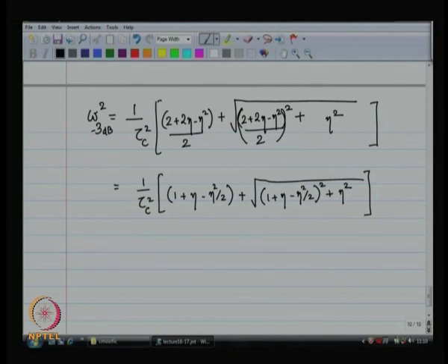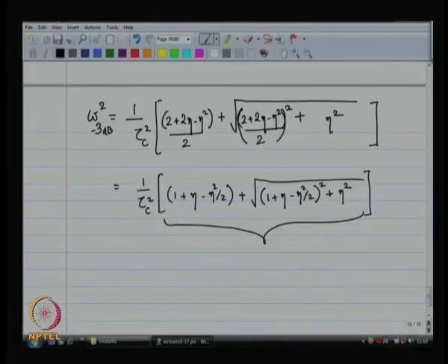So, first of all, when is the bandwidth going to be more than the original? Whenever this factor is more than 1, I am going to get it to be more than the original. And when is it going to be greater than 1? At what eta is this equal to 1? We can solve for that eta. Okay? That is the eta beyond which you are not going to get bandwidth enhancement. You are only going to reduce your bandwidth. You are going to pay a penalty in terms of your bandwidth. So, we do not want that to happen.